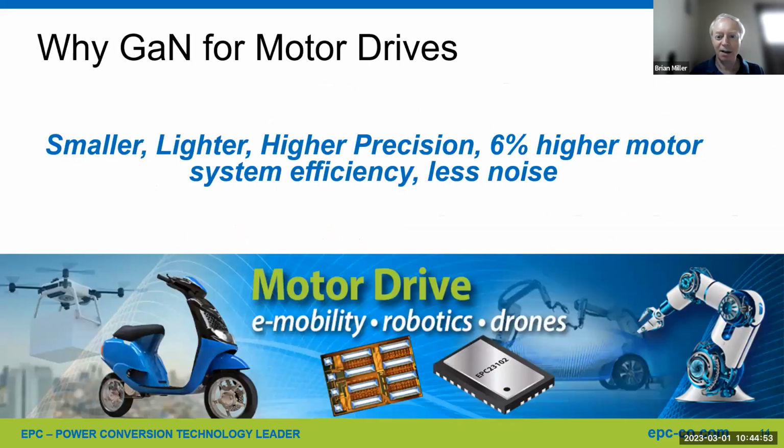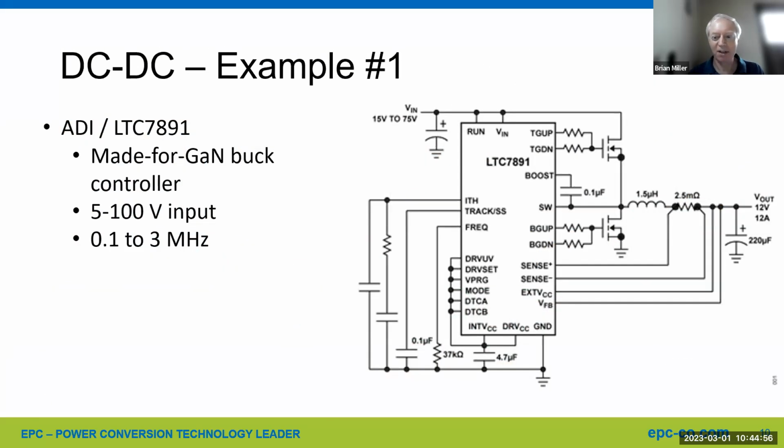Let's see. I'm going back up to this. Just an example schematic here. I mean, this is a half bridge. I think maybe the question is, can you use it as a switch, like a series switch? Yes, you can. You definitely can. You'd have to have a source of 5 volts over the input along with enough current. GaN FETs take more current than MOSFETs, so you have to make sure you have adequate supply. But yes, they work well in series switches, and they're used there in some applications. There's no minimum frequency for GaN FETs.